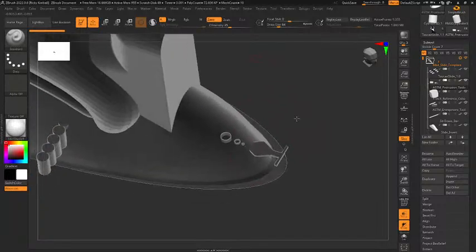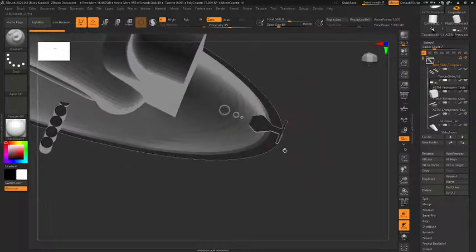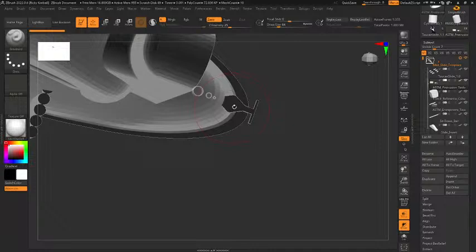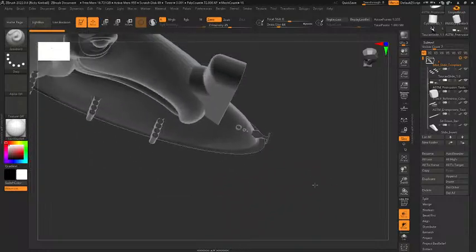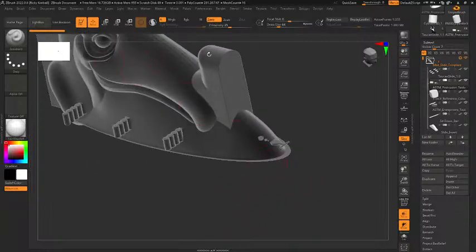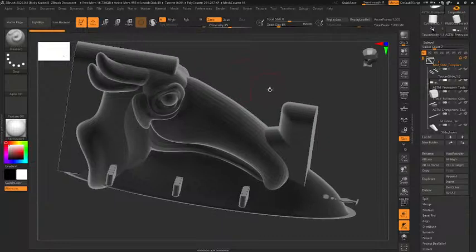This here is an entrapment tool, and this makes sure it's roughly the shape of a kid's head. How they wound up at this, I don't know, but this is what they say is basically a kid's head and shoulders, right? And there are tests that they do, and they basically stick this into any partially bounded opening. A partially bounded opening means that there's some little area. This would be a partially bounded opening where I've got my mouse hovering.